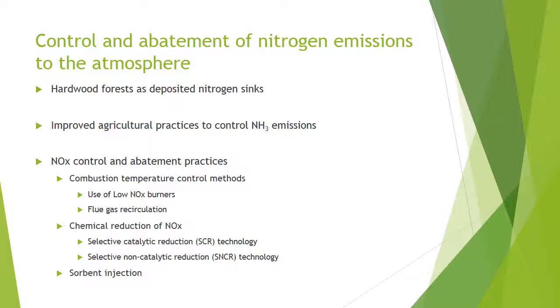There's SCR, which is selective catalytic reduction, and SNCR, selective non-catalytic reduction. SCR is one of the most effective NOx reducing technologies and utilizes a catalyst to chemically react injected ammonia with the gas stream to reduce NOx emissions.